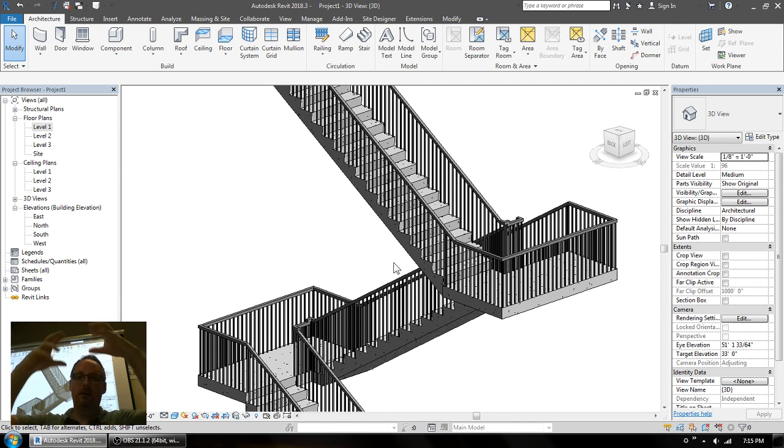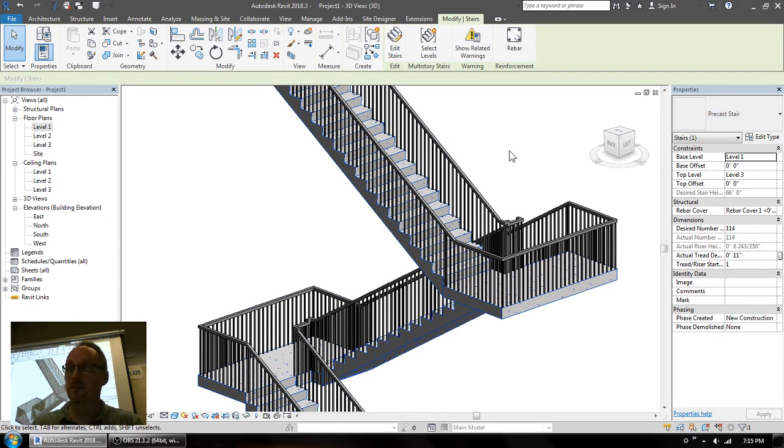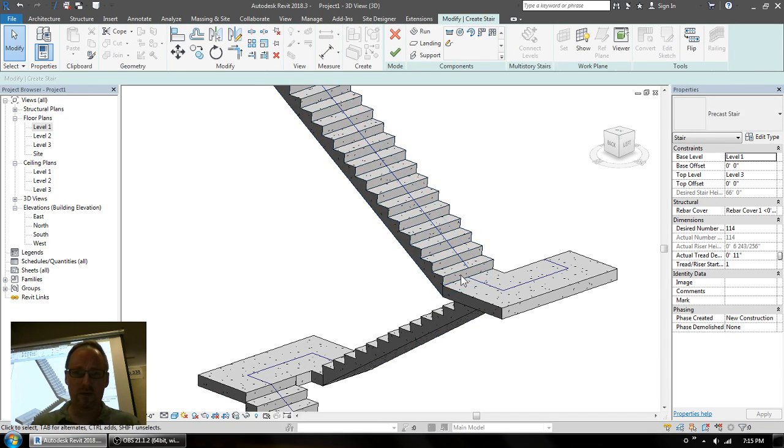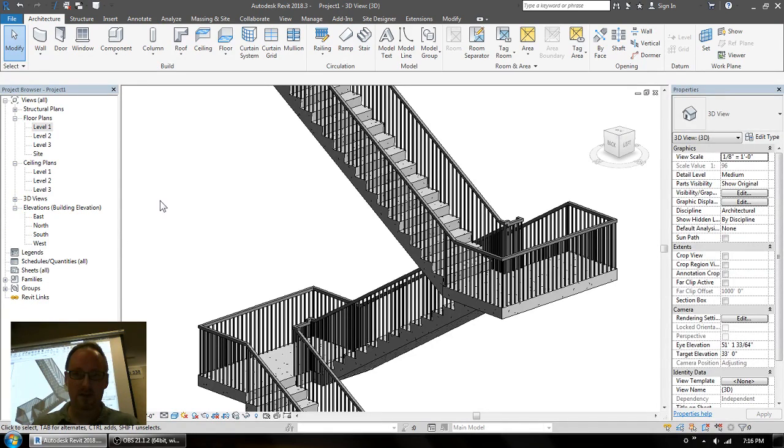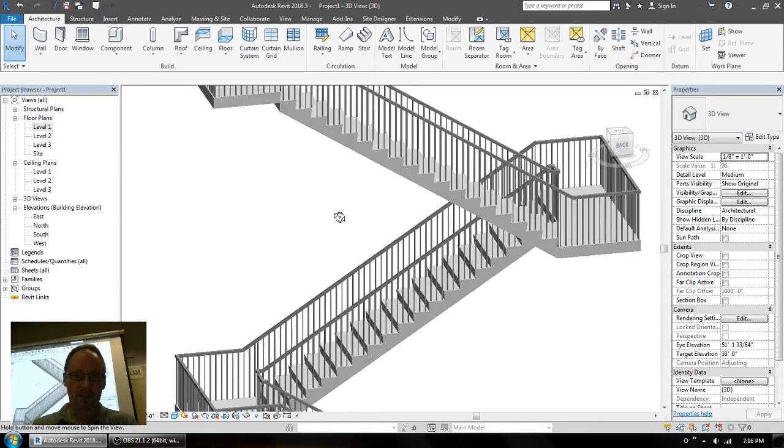With precast stairs, they all kind of bear one on another, and so using the precast stair type, it's still concrete, but you would have those notches made between the stairs and the landing so that you get those opportunities for the upper stairs to bear on a landing and the lower stairs to bear on a landing and so on. So there you can see the railings get created afterwards.